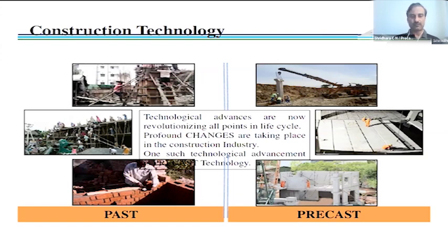Even if you think of casting slabs, hundreds of laborers are required to cast the slabs in cast in situ, and so many wooden poles or shuttering materials are required to cast the concrete and support the slabs. If it is precast, all these slabs will be produced at the factory, brought, and erected using cranes at site. In cast in situ, you require hundreds of people at the site. In precast, hardly 6 to 7 people will be there, as against hundreds of people.